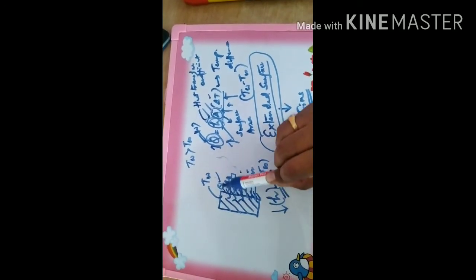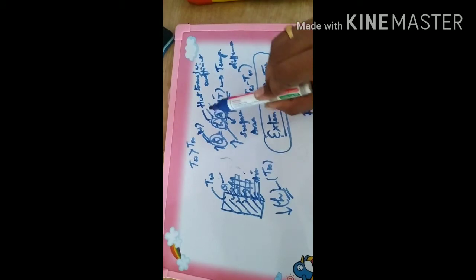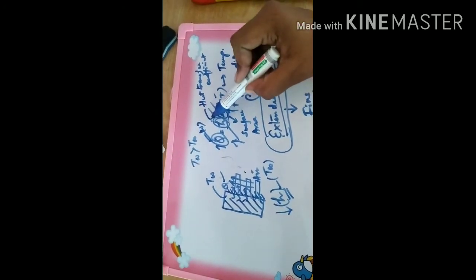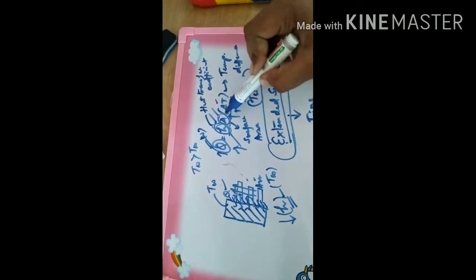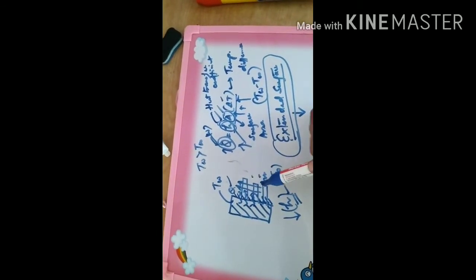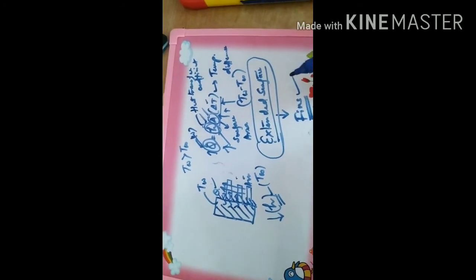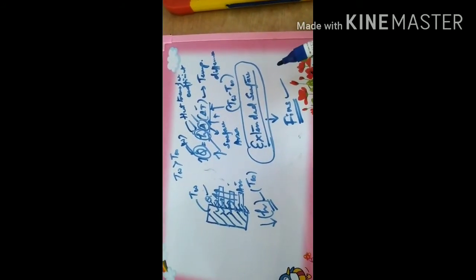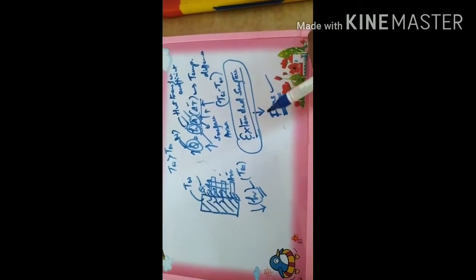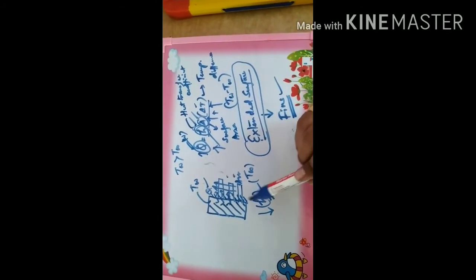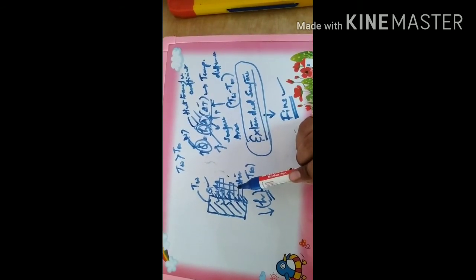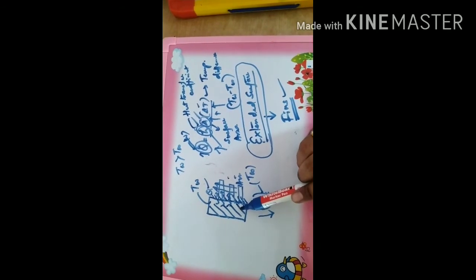Okay, so if the total area available for heat transfer increases, obviously Q gets increased, knowing the limited value of h and the fixed temperature difference. So this is a point of application where we come across the term fins. Fins are nothing but the extended surfaces used for enhancing the rate of heat transfer by convection from a given base surface.